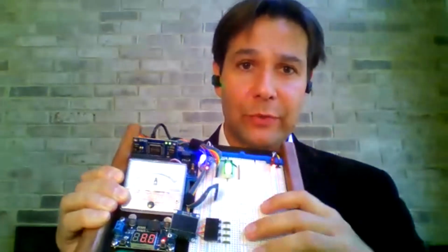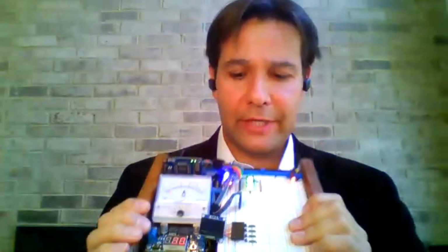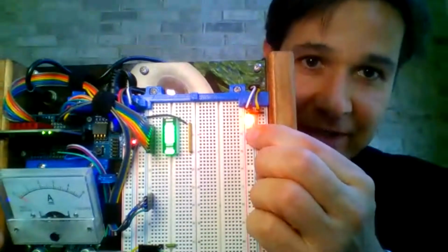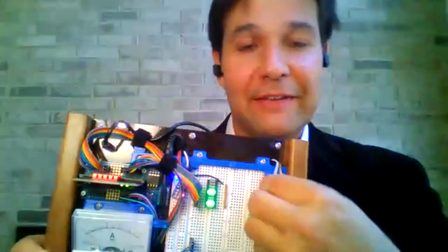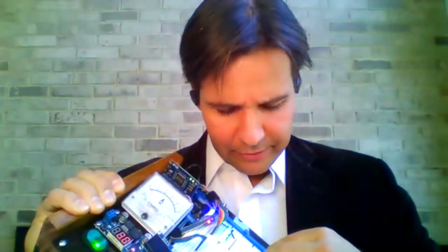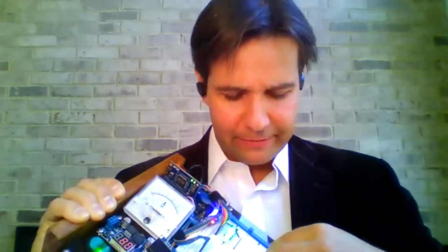A very large breakout board, no offense to the Johnny Mac board, but I think having a large breakout board really helps with the circuits we're doing, particularly trying to get the students to be neat, organize things and spread things out. And these are not electrical engineers for the most part. Another neat tidbit is I found these right at the last minute on Amazon in January: LEDs that have a current limiting resistor built in. So you basically just have the LED, you don't even need the current limiter. Of course, you can't adjust it, but that's a nice FYI, they've got those now.